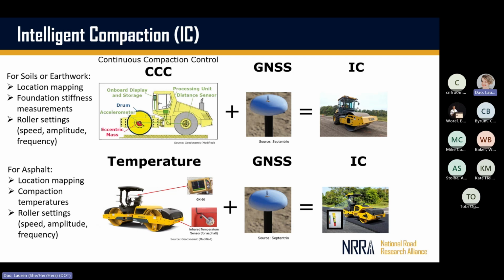Everything I'm talking about today is geospatial, so we've got our GPS tied to all of it. For asphalt, we're able to also monitor our compaction temperatures, which of course is really important when you're talking about asphalt quality.